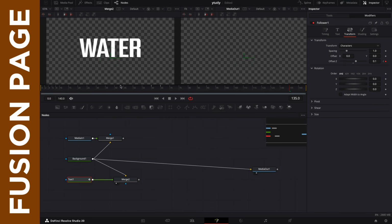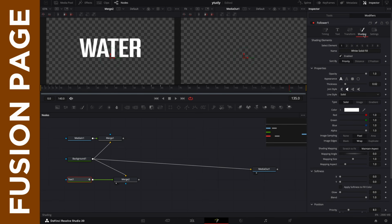But also I just don't want the text to just appear already. I want it to fade in and fade out. So I'm just going to go back to the text node, still under the modifiers, go to shading tab, go to opacity. I'm going to go to frame 60. Keyframe the opacity, then go to frame 0, drop the opacity to 0. So this way it fades in. If I move it forward, you see it fades in one word at a time like that. That's what I want, which is cool stuff.